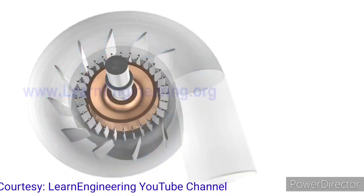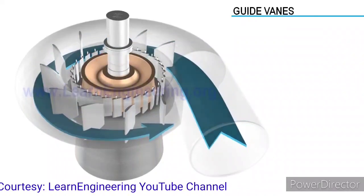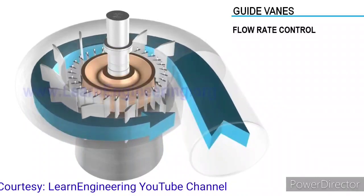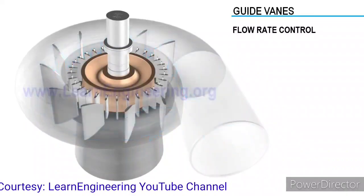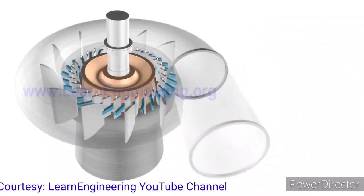Demand for power may vary over time. The guide vane mechanism is used to control water flow rate and makes sure that power production is synchronized with power demand. Apart from controlling flow rate, guide vanes also control the flow angle to the inlet portion of the runner blade. Thus, guide vanes make sure that the inlet flow angle is at optimum angle of attack for maximum power extraction from the fluid.